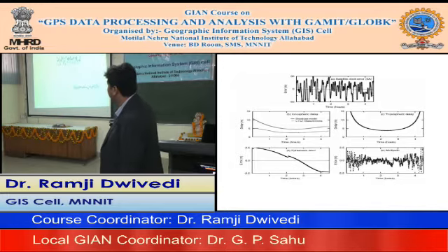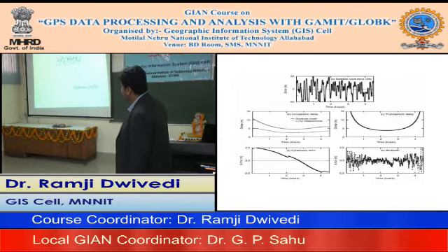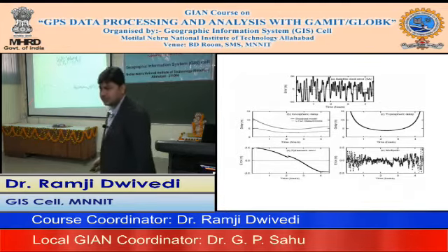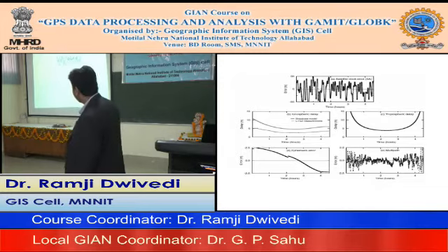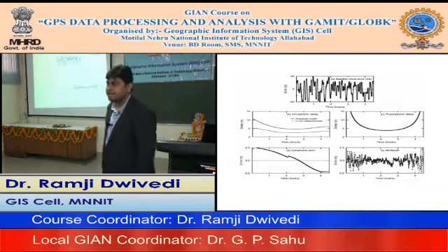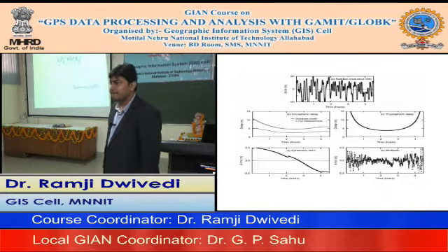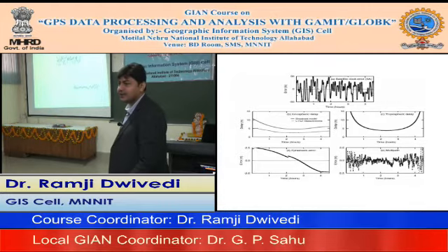What do you understand from those two figures? If you are looking at this figure, what would be those jumps? This is ephemeris errors. If you have ephemeris error, what could be those jumps? Loss of lock would be seen when you plot a certain parameter, and only then could you see the cycle slip.